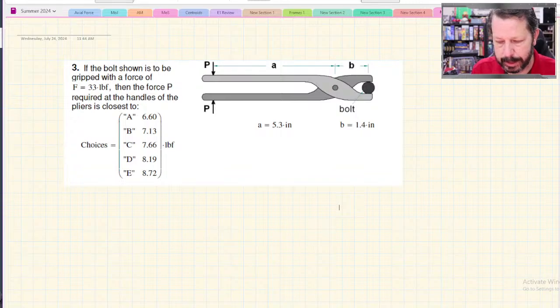So here, these are some kind of plier looking things, and the two halves of the plier move relative to each other. Whereas frames, everything is supposed to stay in the same orientation. Kind of like a truss, except some of the members have forces directly on them, and they're not two-force members. So machines have moving parts, frames are not supposed to have moving parts.